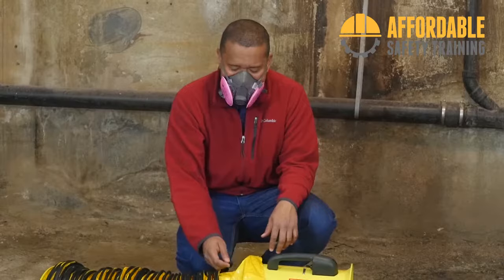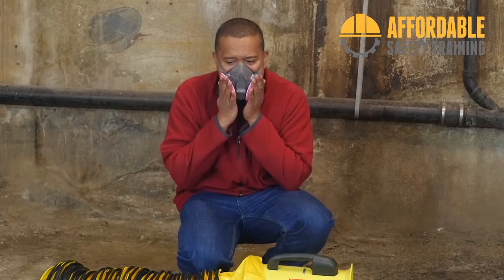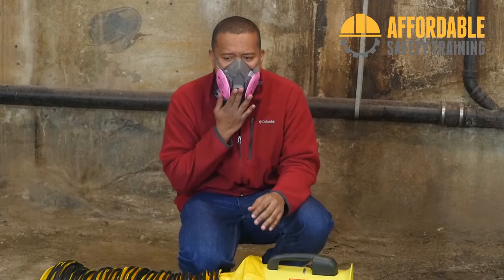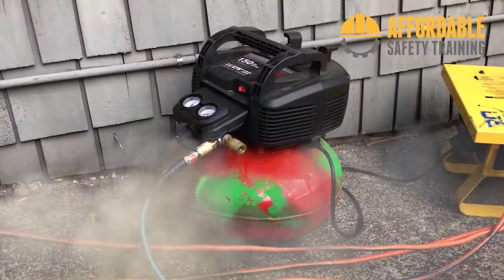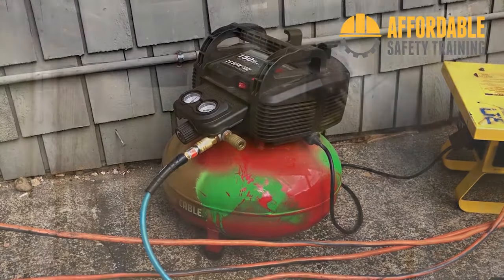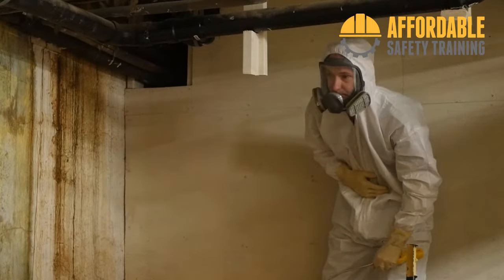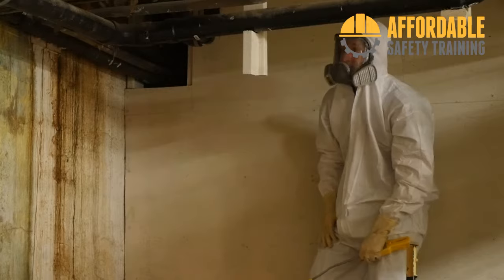Breakthrough occurs when contaminants get through a respirator. This can happen with an expired cartridge, loss of seal, or a sudden increase in hazard levels. In supplied air systems, the air supply source could also become contaminated. When breakthrough occurs, the worker may feel dizzy, tired, or nauseated. An odor may be detected.